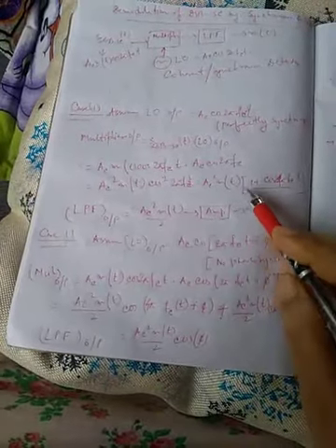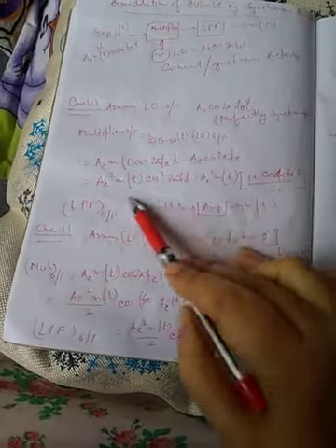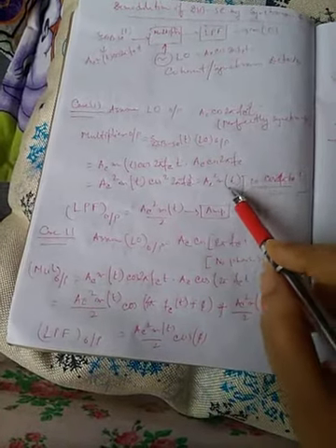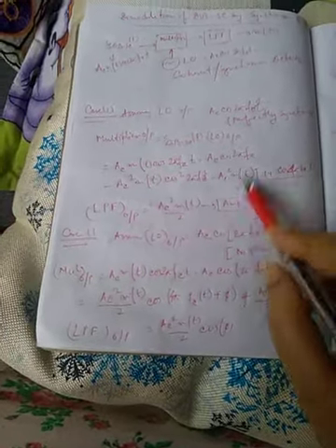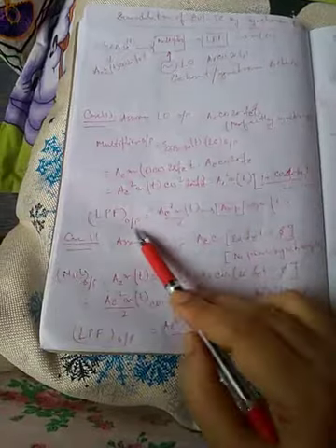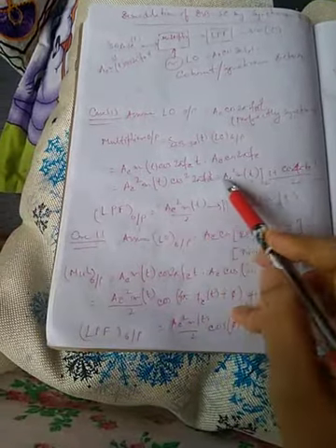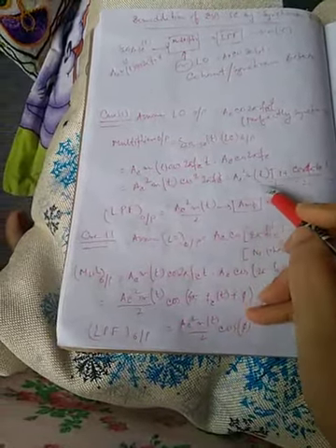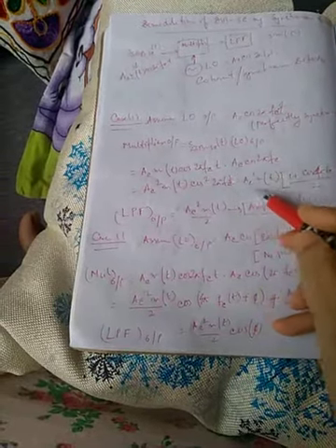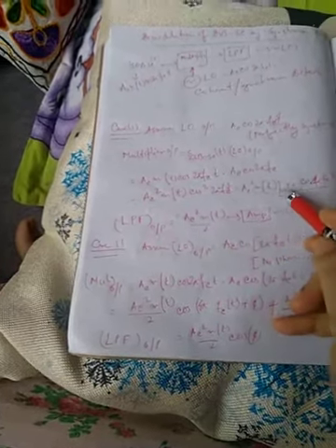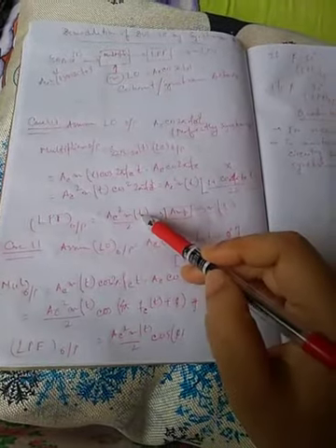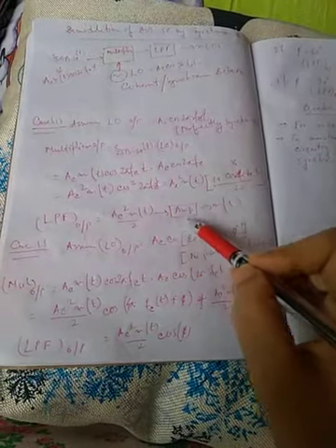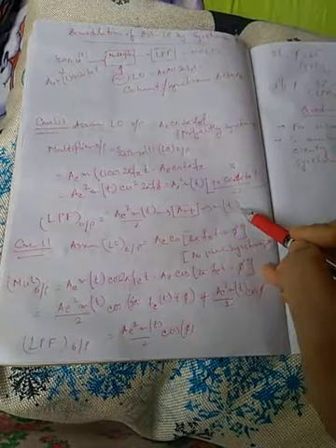So Ac square m(t) into (1 plus cos 4 pi fc t) by 2, that will come from the formula. So my low pass filter will be giving the output as Ac square m(t) by 2, only this part. As it's a low pass filter, it will give the low frequency signal, and the higher frequency signal will get rejected. And finally this term can be passed through an amplifier circuit to generate the original message signal.